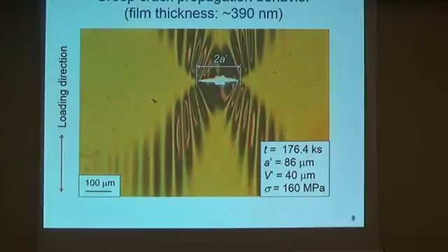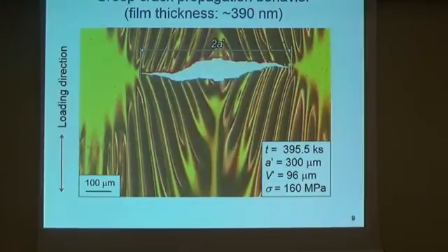And then the crack gradually propagated almost normal to the loading direction, and the crack stably propagated, and then the specimen unstably fractured. Thus the experiments confirmed that the crack slowly propagated even at room temperature in the gold submicron films.